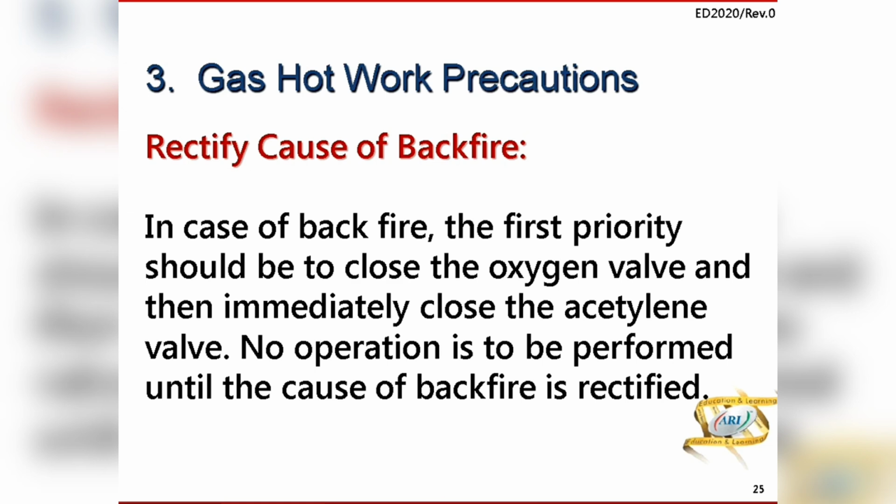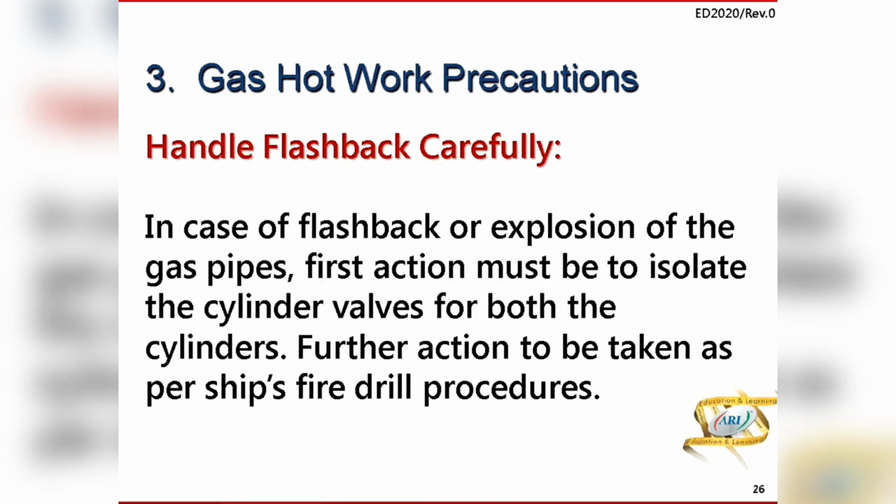Now, when you have a backfire, the first priority should be to close the oxygen valve and immediately close the acetylene valve. No operation is to be performed under the cause of backfire. So, in case of flashback or explosion of gas pipes, first action must be to isolate the cylinder valves for both the cylinders, and the action further should be as per ship's fire drill.